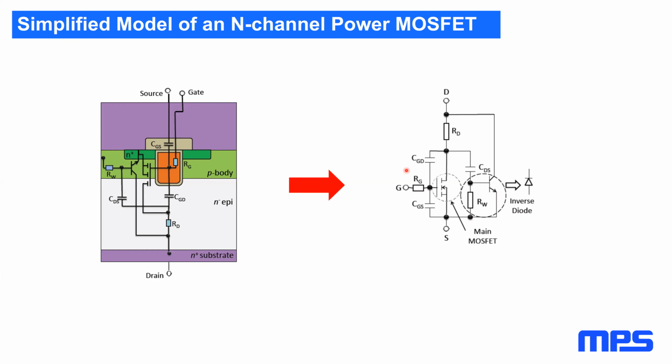That might not be practical, because if you connect a motor directly to a battery, the initial current, which is basically the stall current of the motor, the voltage divided by its resistance, there's really nothing to limit that current. You could be getting hundreds of amps out of a battery for a few milliseconds. Whereas with an IC and a motor driver, you may not be able to get there. So the solution, if it's possible, is to use a bigger motor driver, a higher current limit, and if it's power MOSFETs, really big power MOSFETs.